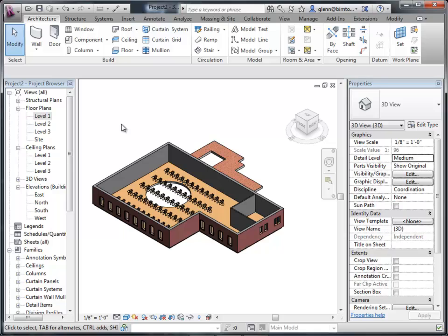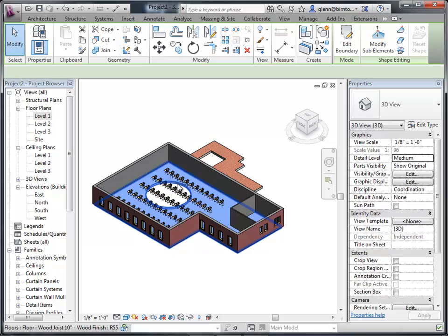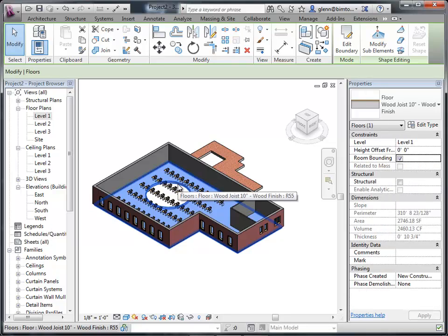So just say that, and back here, let's go. No, where do you select the boundary for? Or what tab? What happens is as soon as you've selected the floor, it's one of those weird ones where it'll only show up if the floor is selected. So select the floor, and then you'll actually have, it says Modify Floors. There's an Edit Boundary choice down here. So it's only when the floor is selected.